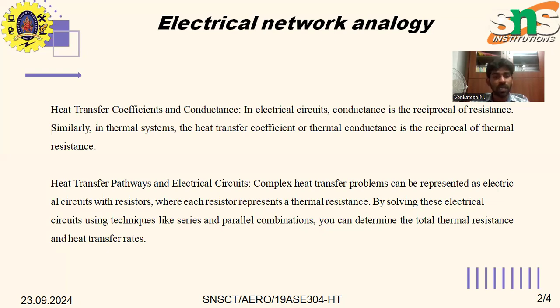Heat transfer pathways and electrical circuits: complex heat transfer problems can be represented as an electrical circuit with resistors, where each resistor represents a thermal resistance. By solving these electrical circuits using techniques like series and parallel combinations, you can determine the total thermal resistance and heat transfer rates.